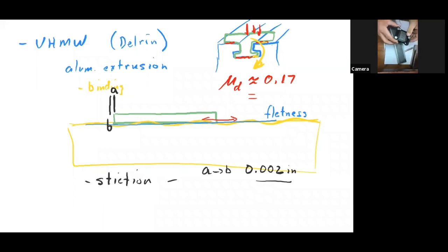So this is a linear stepper motor, and you can see the tooth structure here. This is where all the magnetics are. There's a tooth structure built into this bar of steel, and there are little roller bearings here that roll along this surface and give you an air gap. These little roller bearings are moving along the sides, and so they're carefully controlling the air gap. I'm going to put this back on now.